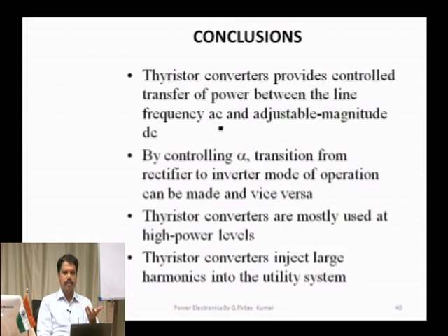The frequency increases. Frequency increases means your impedance or reactance increases, so the voltage drop is more. And also if you add up all the harmonics and see the resultant voltage, it will not be sinusoidal. And all the devices have been designed so that your source voltage must be sinusoidal. So, it pollutes the power system. This is one of the disadvantages of using power electronic devices. Power electronics has many more advantages.